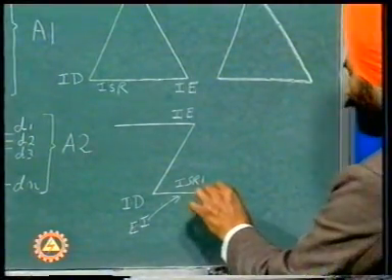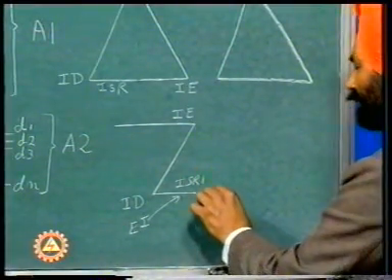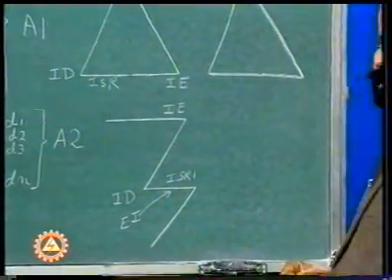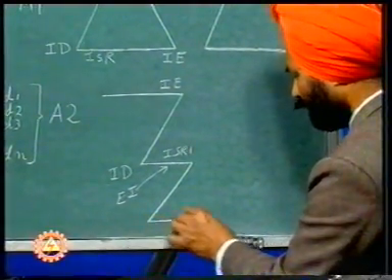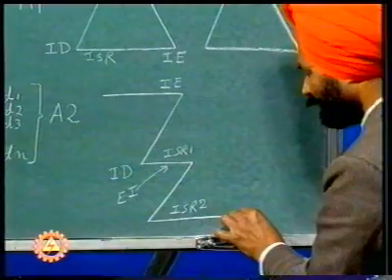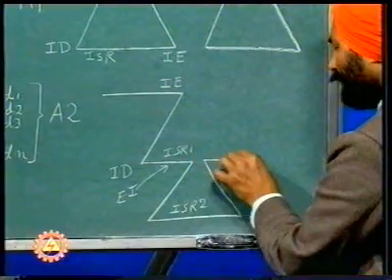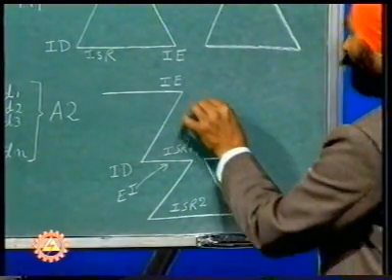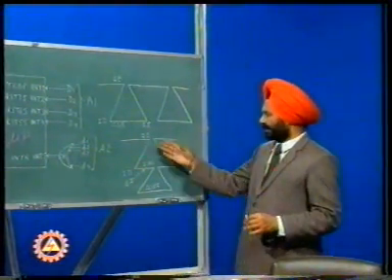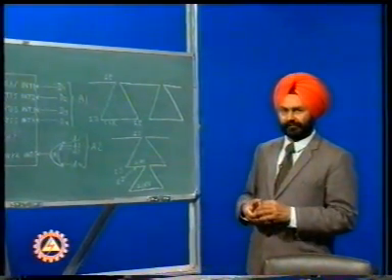Now, if another interrupt comes and that may be of higher priority compared to the one that was being serviced, the microprocessor will suspend the service of the earlier interrupt and will branch to the second subroutine, say ISR2, to serve the later interrupt. After completion of the service of the second interrupt, it will go back to serve the earlier interrupt, then completing the service of this, it will go back to the main program. This process of interrupt service is called nesting of the interrupts. The nesting of the interrupts can be carried to several levels.